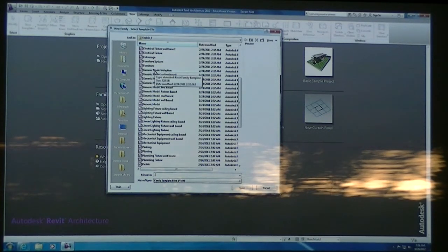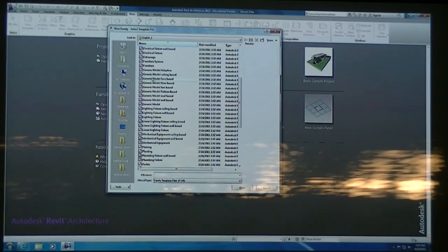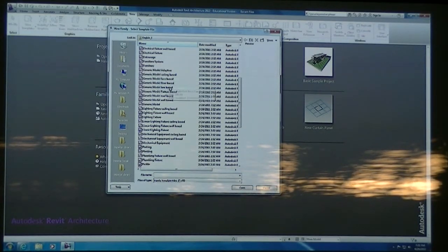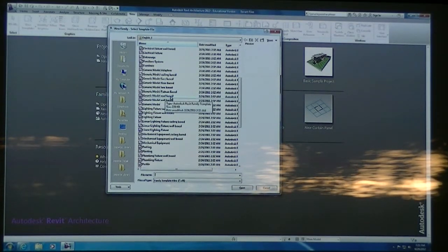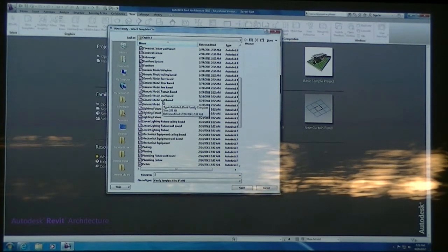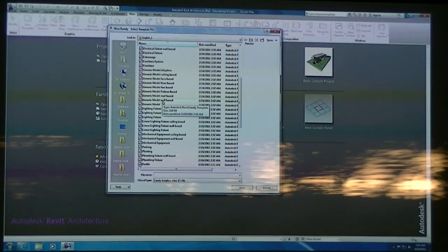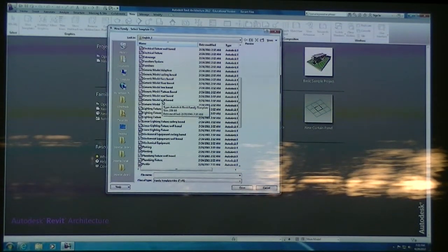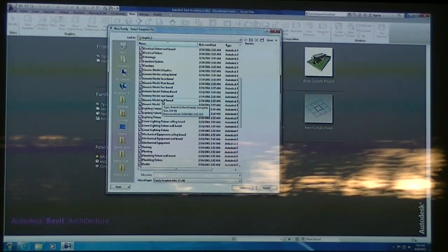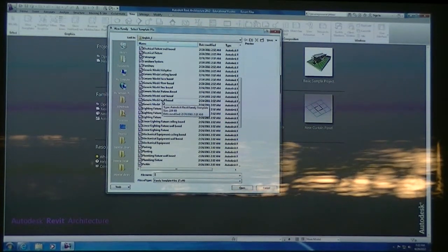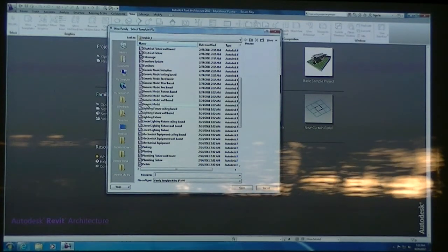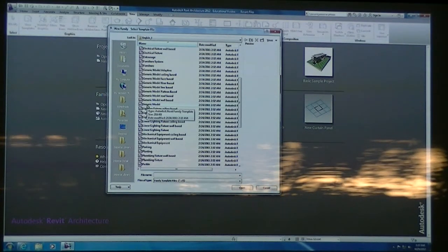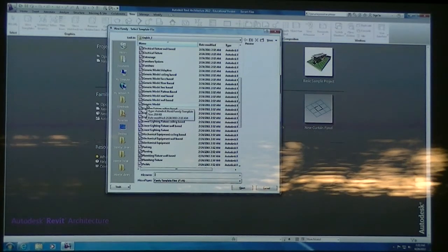Remember, we've used the generic model adaptive, but once you get into these other ones that are ceiling-based, face, floor, line, pattern, roof, and wall-based, those all require that when you bring this component into the project environment, if it's a generic model floor-based, it's not going to be placed until you have a floor available for it to be placed on. So a lot of times I will just do generic models, because then there's no host element, and it's kind of this free-floating thing that you can place however you like.